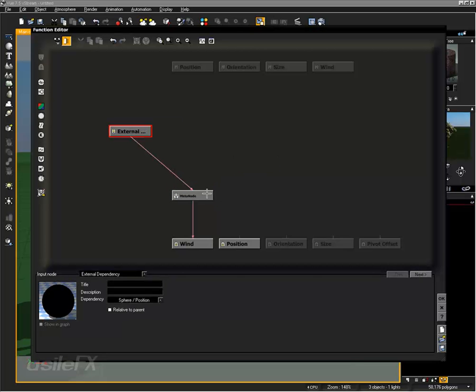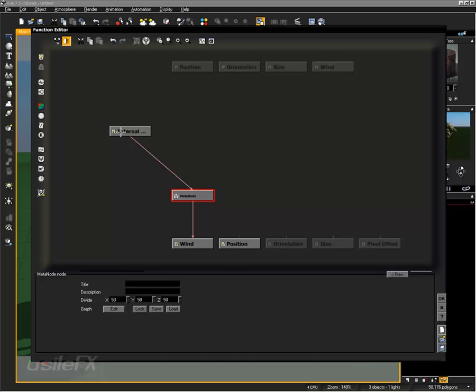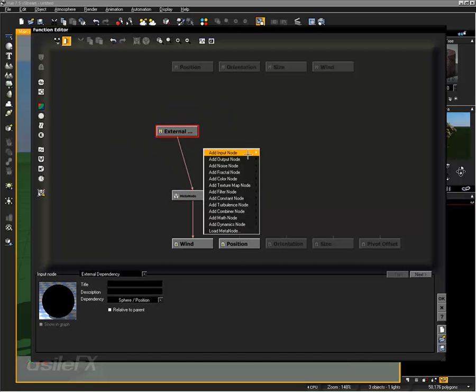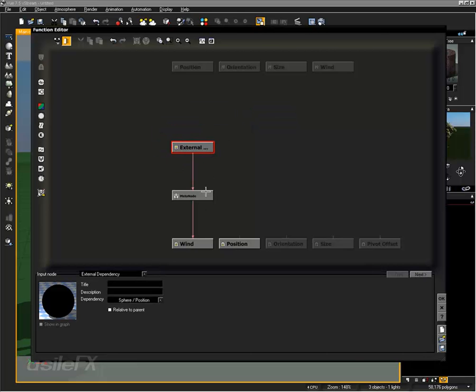So a lot of the tools I've decided to add in the vector3 input node and just make that connection have to be a manual add input external dependency and then select what you want to connect it to. Because otherwise, a lot of the tools were not refreshing. Sometimes in the material editor, things would show up, but when you rendered it, they wouldn't work correctly. So you may not want to include your external dependencies within the metanode. Hopefully in future versions it becomes fixed, but I have noticed it kind of bounces back and forth whether it works or not.